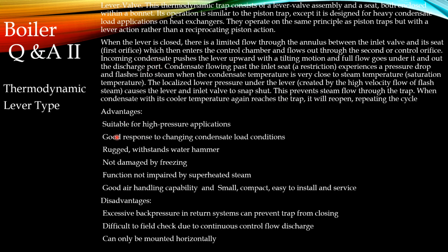The advantages: it is suitable for high pressure applications, with good response to changing condensate load conditions. It is rugged, withstands water hammer, and will not get damaged by freezing. Function is not impaired by superheated steam, so it can be used for high pressure superheated steam. Good air handling capability, and it is small, compact, easy to install and service, and can be used for initial startup.